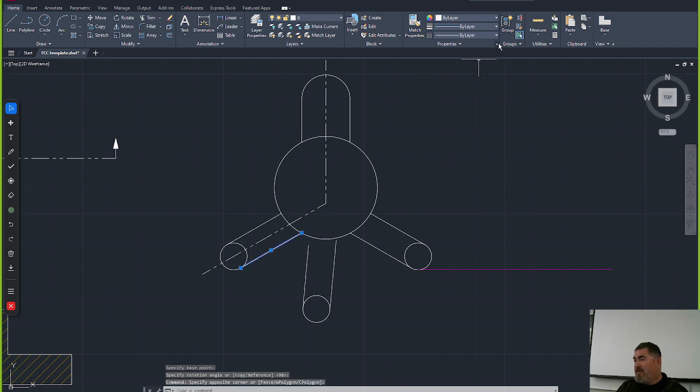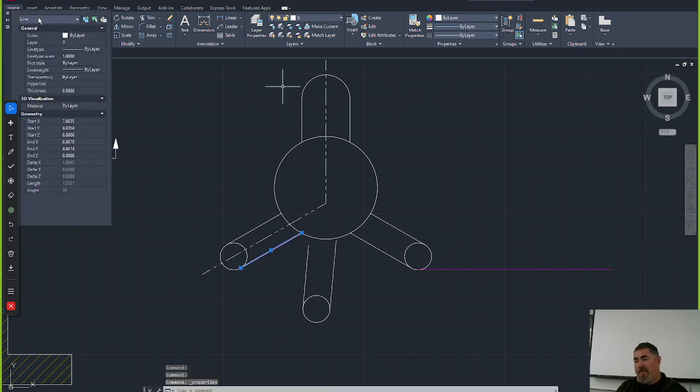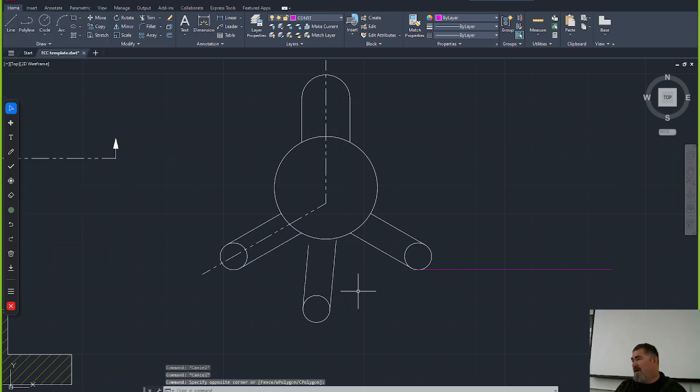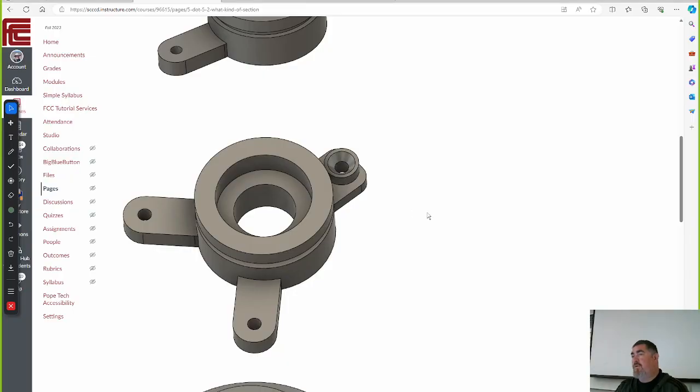And if I do a selection, I can see it only picked one thing, because if I pick more than one thing, it's going to give me the parentheses. So a lot of times if I want to copy something into a weird position to do something, but I want to leave the originals there, I make a copy of it, put it down right on top of it, and then select the previous thing to move it. Okay. Any questions on that?